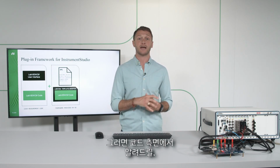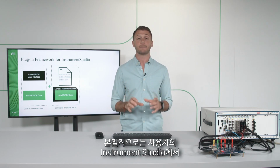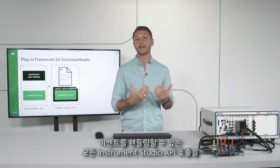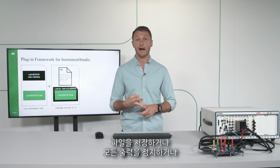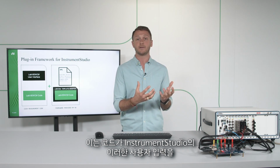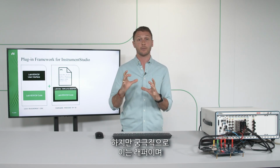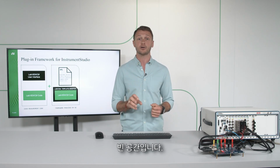Then, on the code side, we're going to give you, I'll call it a wrapper. It's a template, but essentially, it's going to include all the Instrument Studio API calls that allow you to handle events from Instrument Studio, from the user, like saving your file, stopping all outputs, or closing Instrument Studio. That gives you a way to build into a state machine how the code will handle those user inputs from Instrument Studio. But ultimately, it's a wrapper, and there will be a blank space in the middle for you to input your functional code.